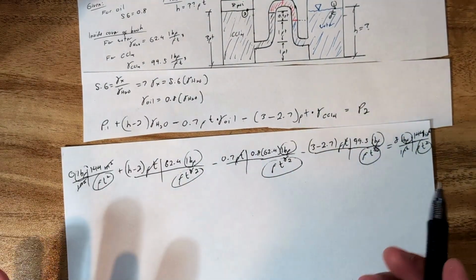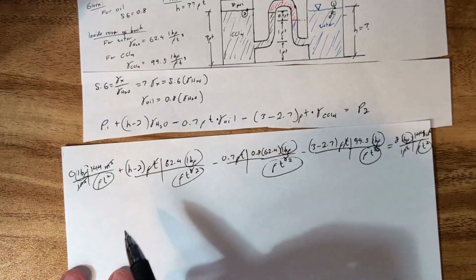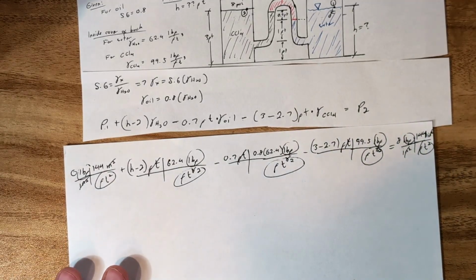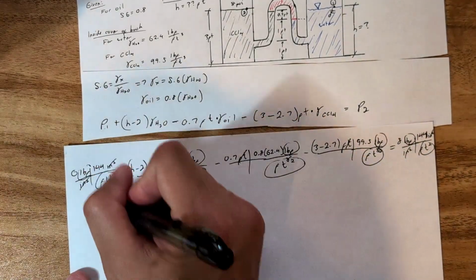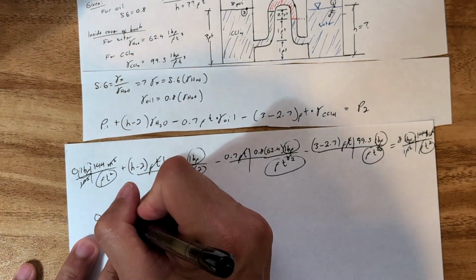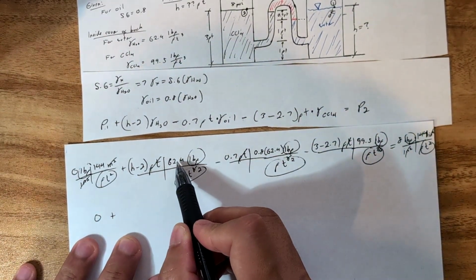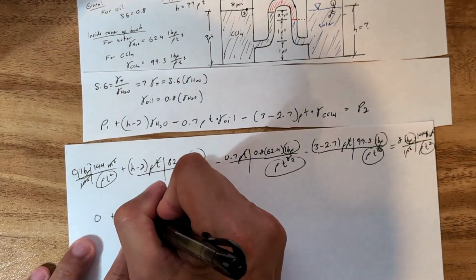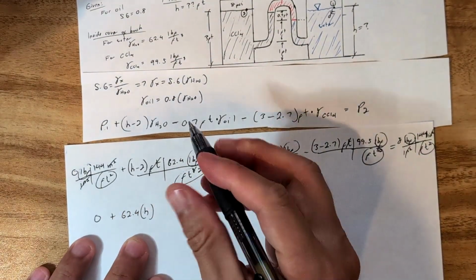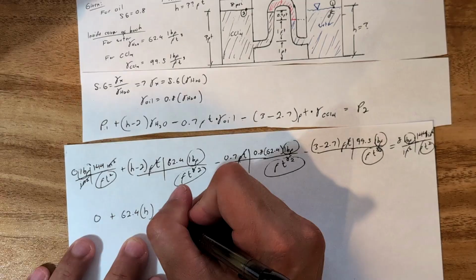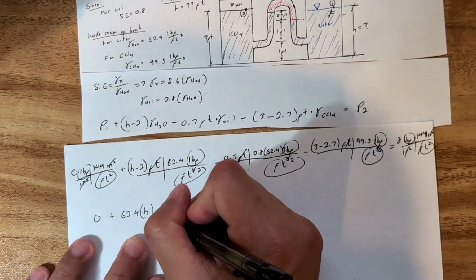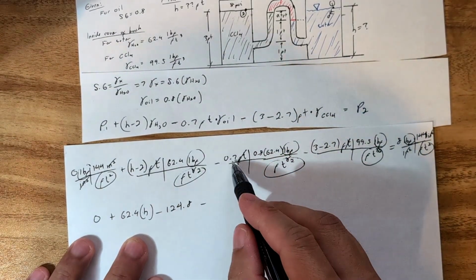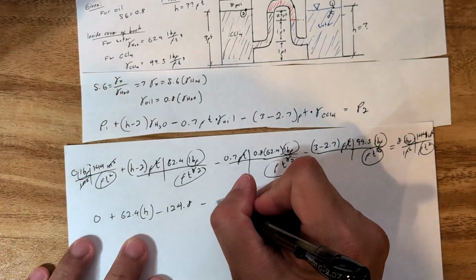once you show your units, usually your teacher will want to, as long as you're clear with your units, you can just pretty much do algebra at this point and just work with the numbers. So this is going to be 0, and then plus, if we distribute 62.4 to this term right here, it's going to be 62.4h. I'm just going to put a parenthesis to make it clear that's a variable that we want, minus 62.4 times 2 minus 124.8, and then minus 0.7 times 0.8 times 62.4, that's going to give you